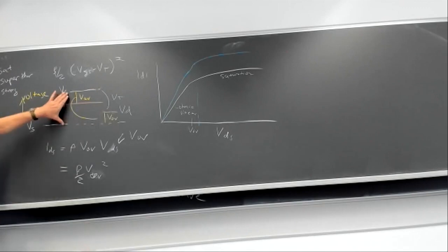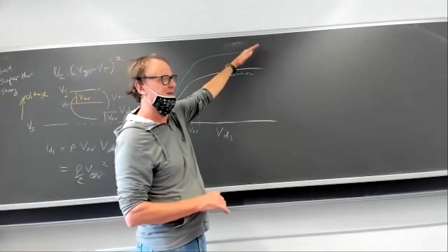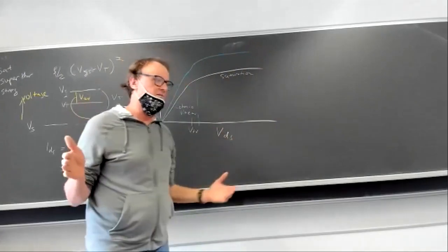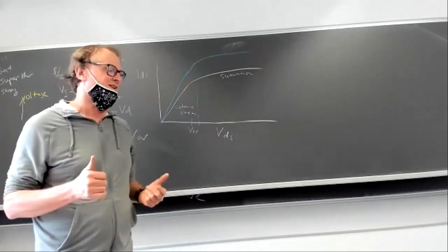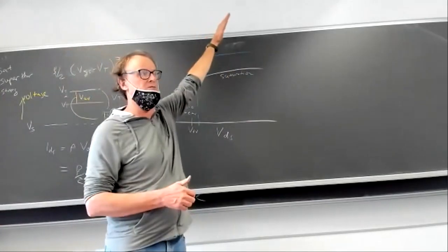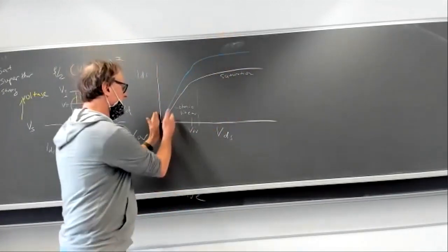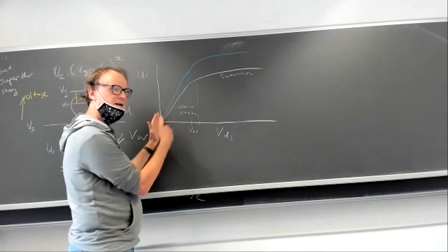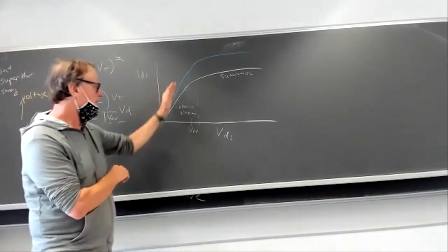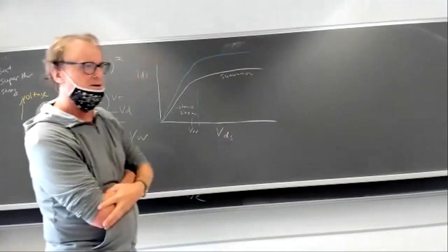See, the bigger the gate source voltage is, the bigger the voltage that you saturate at. That's what happens above threshold, right? So if you put a big gate source voltage, like 4 volts, then the overdrive is going to be like 3 volts. The transistor will be linear for like 3 volts above the drain source voltage. In subthreshold, it all happens within 100 millivolts or so. It's a different mechanism, right? Giacomo will show you next week. But above threshold, the harder you turn on the transistor, the longer the region that is linear.